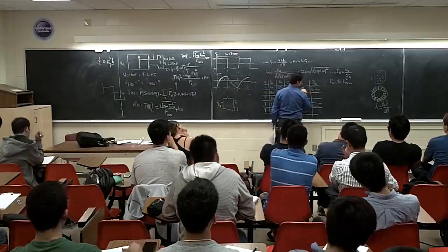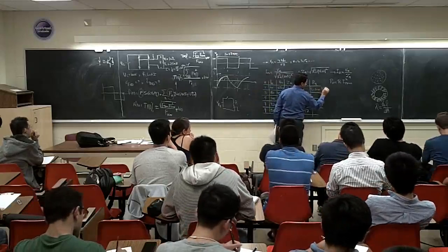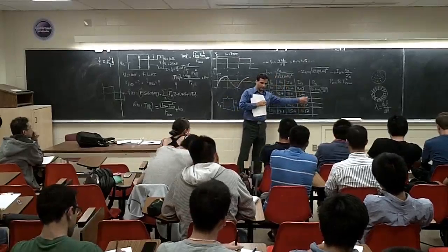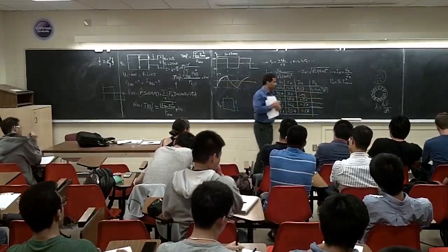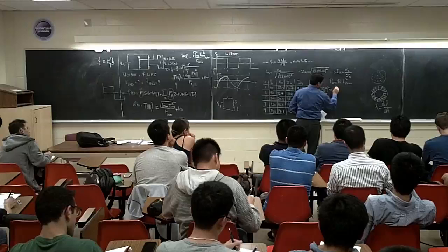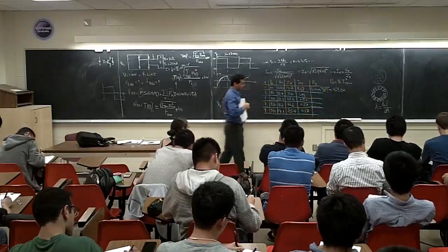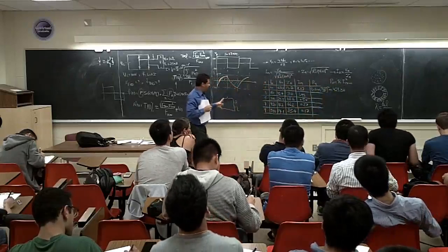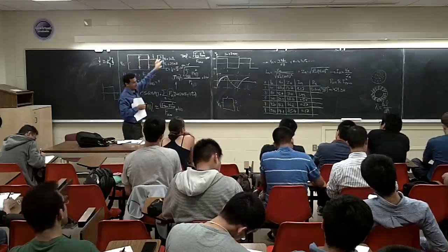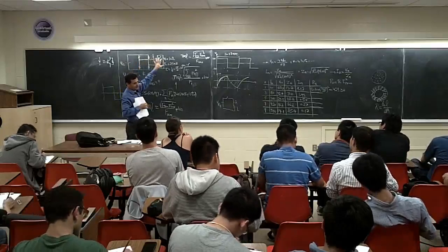So it's going to be this one divided by square root of 2. Why did I divide by square root of 2? Because these are maximum values, right? To get the RMS value of this current, divided, to the power of 2, basically this one is going to be 429.31. This is for the first harmonic. This is the power that is going to be transferred from here to here, right? Almost 500 watts is coming through the first harmonic.